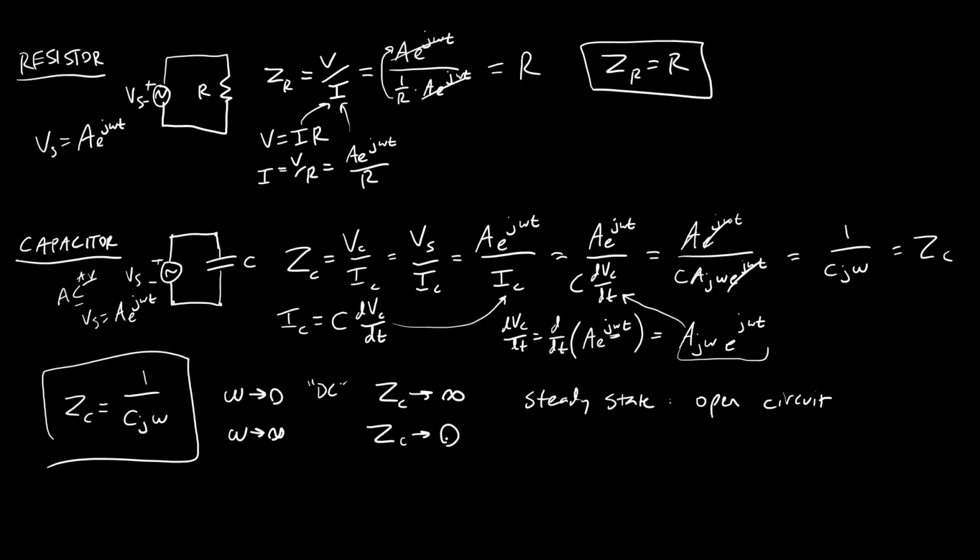So the capacitor is going to act like a short circuit. If you have an extremely high frequency signal across a capacitor like this, it's like the capacitor just isn't there at all. Before, we thought about how things behave in steady state, with essentially a 0 frequency signal. We haven't thought about this high frequency limit.